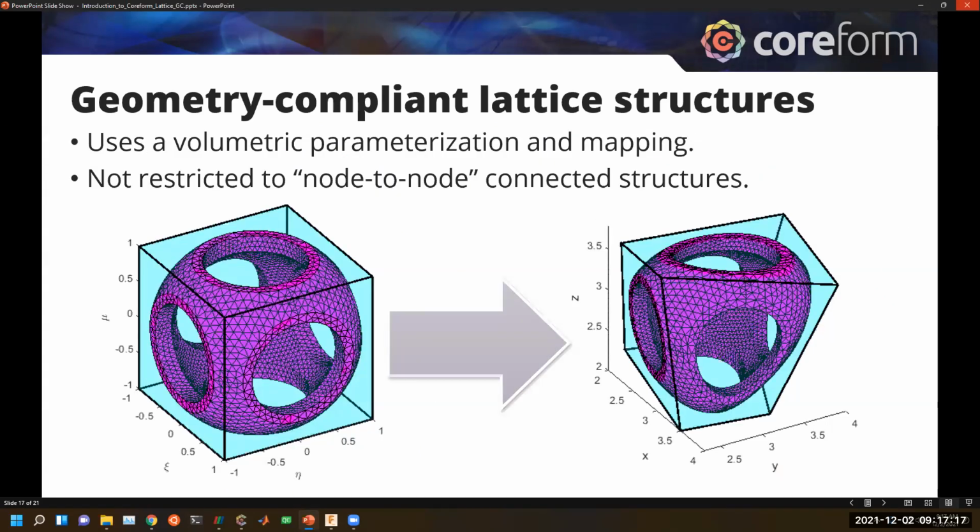And as a keynote, again, what's happening under the hood is we're just borrowing a lot of concepts from finite elements. So we take the geometric mapping of a finite element, and I've shown here the unit cell as a tessellation of triangles. So each point in this tessellation has a mapping then to the element in its deformed configuration when you've meshed the part.